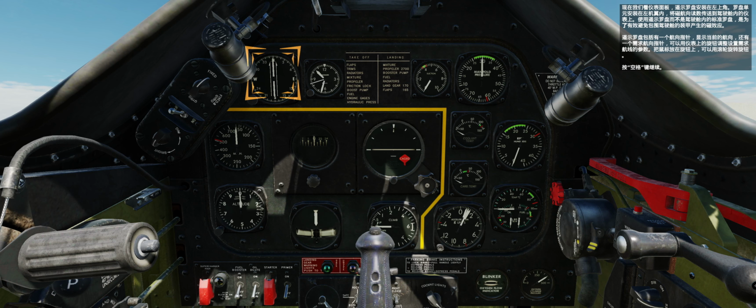The remote indicating compass includes a heading needle, which shows the current heading, and a desired heading needle, which can be turned using the indicator knob to set a desired course reference on the indicator. To turn the knob, you can simply roll the mouse wheel over it.